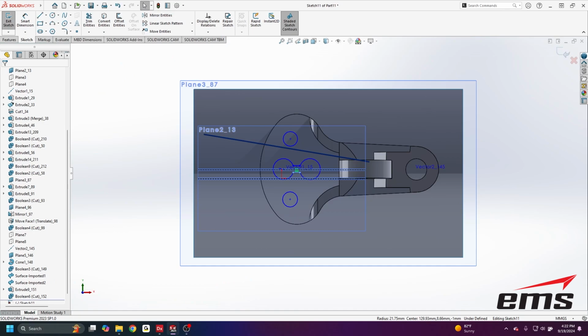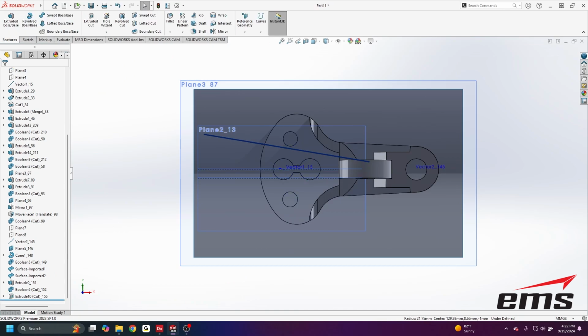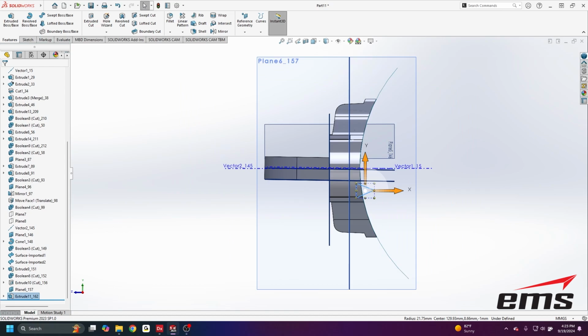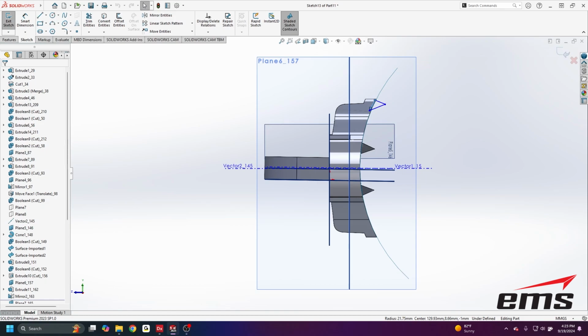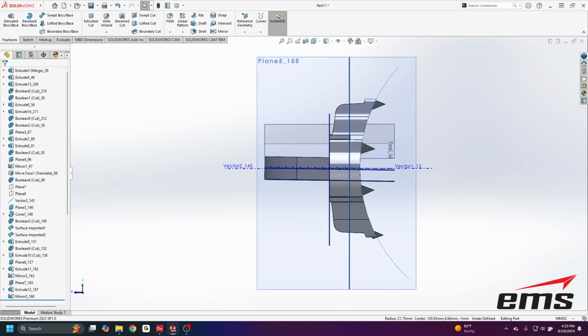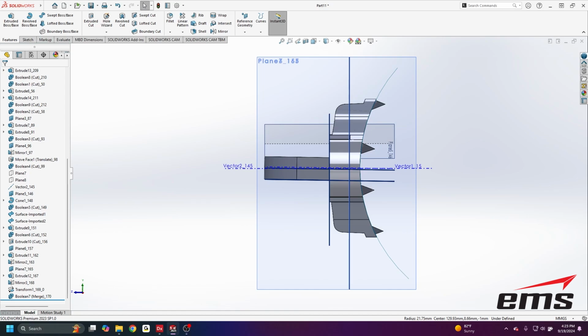Now not everything goes through automatically, because Design X Go does some things a little bit differently than SolidWorks, because it has the scan data as reference to do certain things. I don't want to get too technical, but if you know how this live transfer works, you can minimize that. What happens is it will stop and ask you to do something, like maybe cutting a surface. SolidWorks might require to know the normal direction or which side to keep. That may not come over in the live transfer, so you just have to make that selection